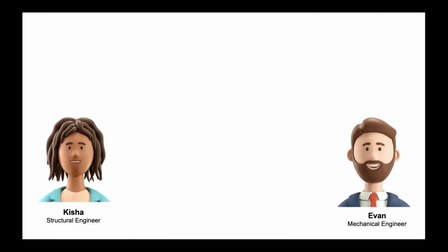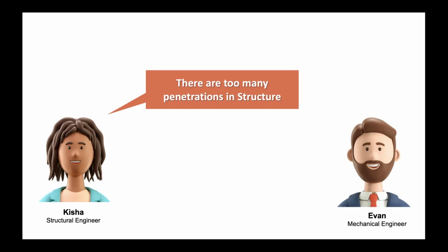Okay, let's take a look at another example. So mechanical, structural, lots of coordination issues. Of course, a person could argue it depends on whether the model is a design intent model or a constructible model. So that bears on some of this as well. Solibri can be used for either, but obviously you have to rationalize its use, whether it's a design intent model or an actual constructible real world model created perhaps by the contractor. But in any event, this is your typical too many things running through things scenario, structural and mechanical, right? So you've seen this before.